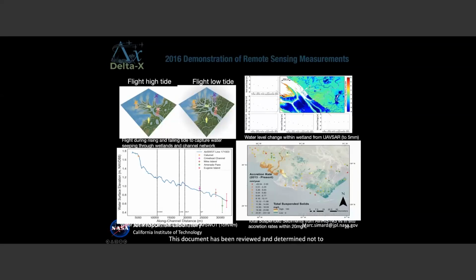So the river, which is this one right here, over a span of about 25-30 kilometers, has gone down by about 1 meter. So here we're talking of slopes on the order of 1 to 3 centimeters per kilometer. So these systems are extremely shallow, and this is very challenging for measurements. So this type of measurement that you see here has never been seen before, right?